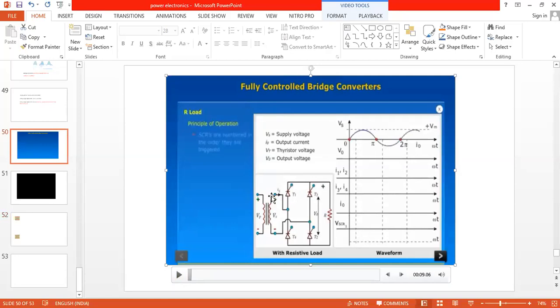If you see the fully controlled rectifier, why is this transformer used? What is the name of this transformer? It is not step up or step down operation performed by this transformer. It is called an isolation transformer with the ratio 1:1. This transformer connects or disconnects the circuit. So directly AC voltage can be applied to the power SCRs, but here in order to provide the isolation, if required, this transformer is used as the isolation transformer to connect and disconnect the circuit. Okay, the ratio is 1:1. We already took the working principle of this circuit, but I want to show you the graph practically.